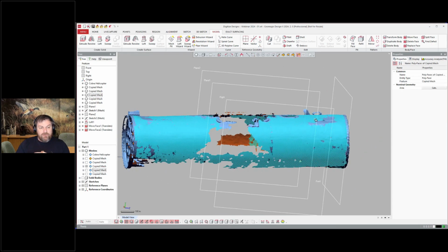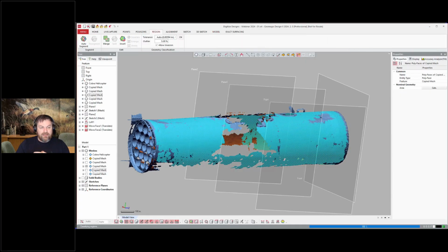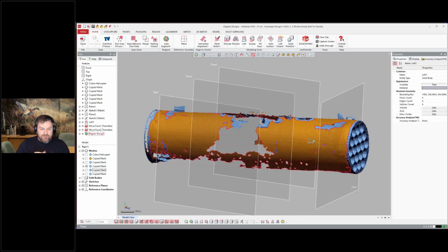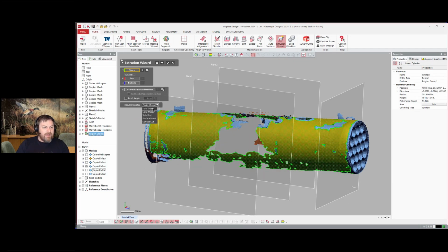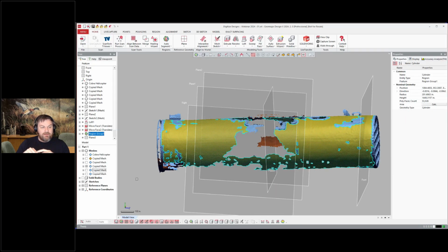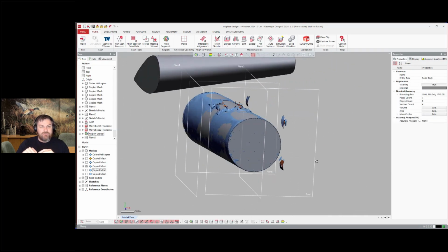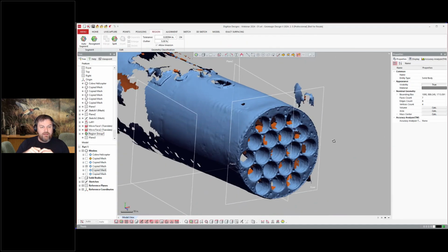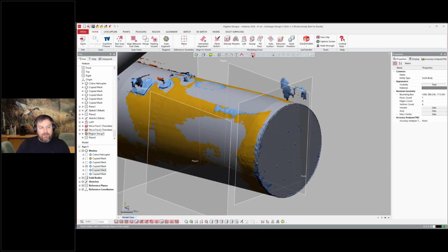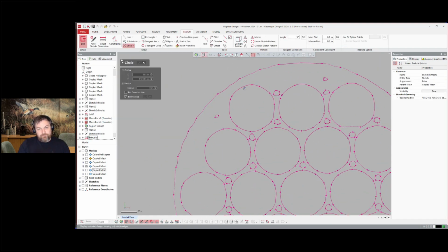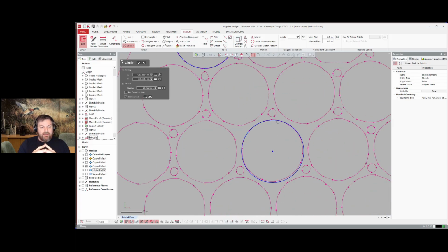Now what we're doing here with this component is I am selecting those polygons with a tool there, and then I'm actually creating a region there. And then instead of modeling this manually, I'm telling it to go ahead and use what we call a wizard there. So I said create an extrusion from this area. And what it did is I grabbed that region, said create extrusion, and it just automatically drew the sketch and created it for me.